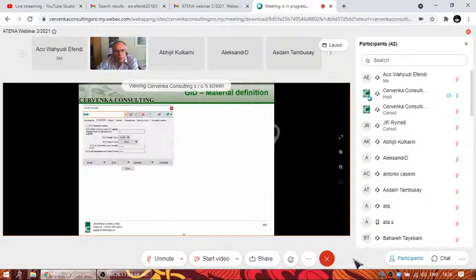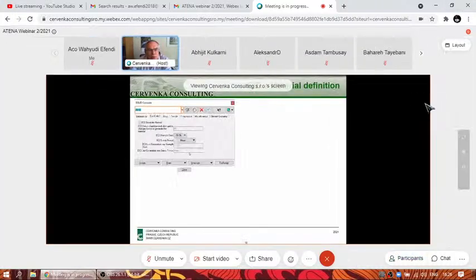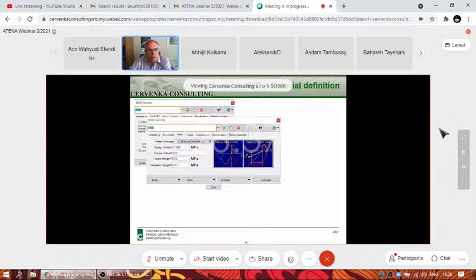Now about the material parameters. In terms of material parameters in ATENA, let's have a look at how it affects. Let's have a look, for instance, at the concrete material parameter, which, as I said, is the main material we are working with in ATENA. So in ATENA, you can generate the material properties based on the strength classes or the cylindrical strength or adhesive strength of the material.